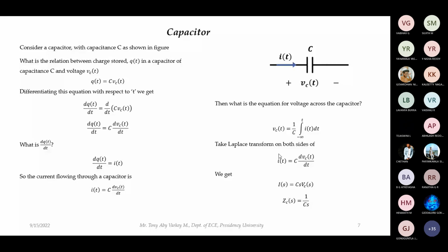That is why normally people will tell capacitor will block DC. So in your analog electronics class, they might have told you that coupling capacitors are used in your amplifier. That is why it is used, because it will block DC. It will pass only AC to go to the transistor. Whatever biasing input voltage that you are giving will not interfere with the amplification action of the transistor. That is why you are providing capacitors as coupling, because it will block the DC.